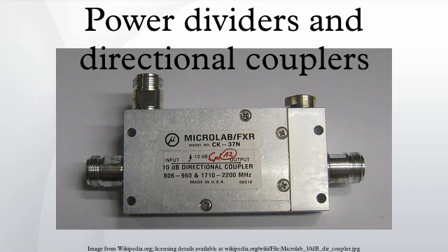Hybrids. Applications of the hybrid include monopulse comparators, mixers, power combiners, dividers, modulators, and phased array radar antenna systems. Both in-phase devices and quadrature hybrid couplers may be used for coherent power divider applications. An example of quadrature hybrids being used in a coherent power combiner application is given in the next section. An inexpensive version of the power divider is used in the home to divide cable TV or over-the-air TV signals to multiple TV sets and other devices.